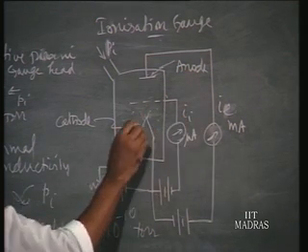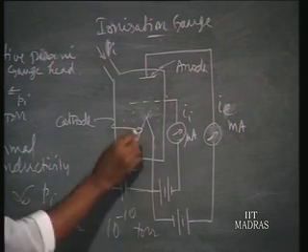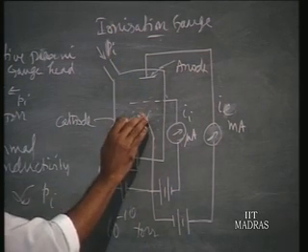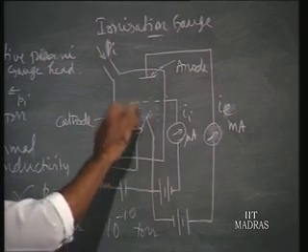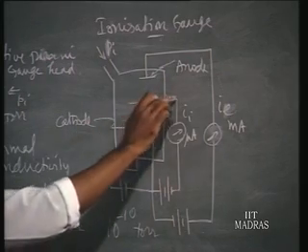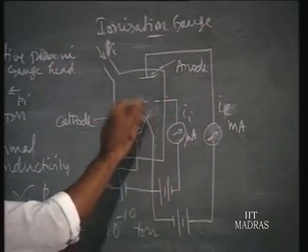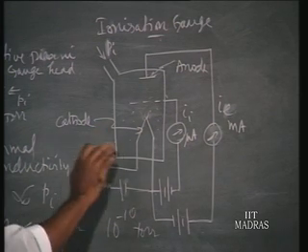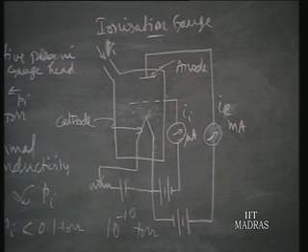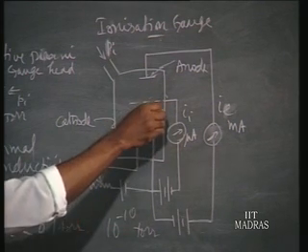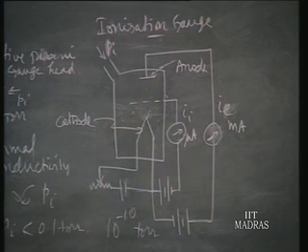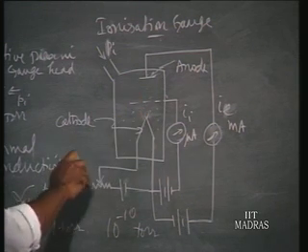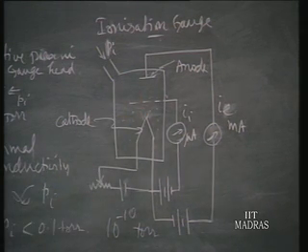But that IE will not be changed by the number of hits. The racing electrons hit the gas molecules, and the number of molecules hit decides the current flow. The number of positive ions indicates the number of particles hit by the racing electrons. So in other terms it indicates the vacuum pressure. More pressure means more molecules come here, so that's why it indicates the vacuum pressure.